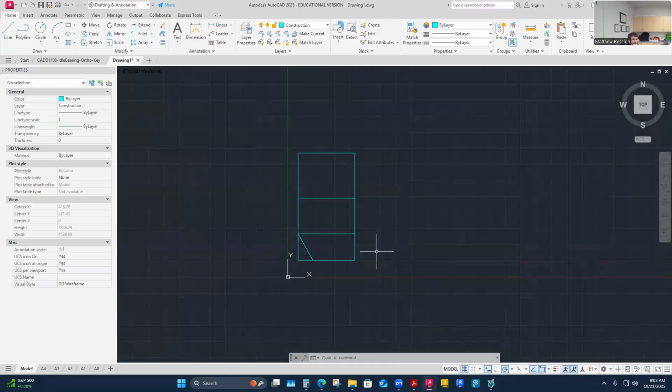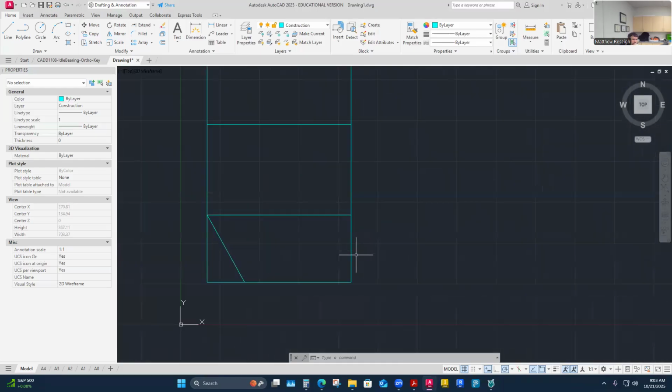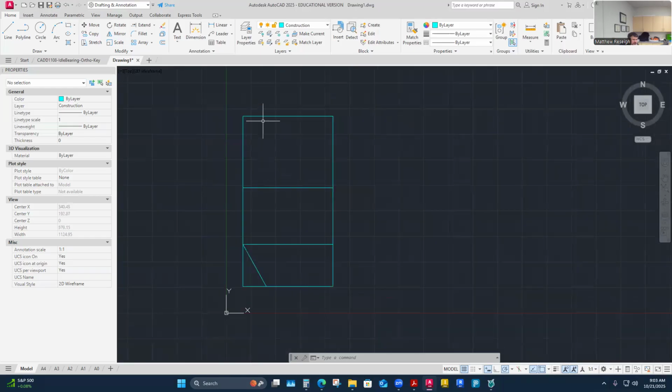You said the width was one. Yeah, this one here, the depth 140. Yep, that's 90 plus, that's the outermost. It's really only that dimension way up there on the little sloped plate with the holes in it. But it's that linear length plus the 2 radiuses, 25 and 25. So 90 plus 50, 140. And I think I'll start drawing the front view here.